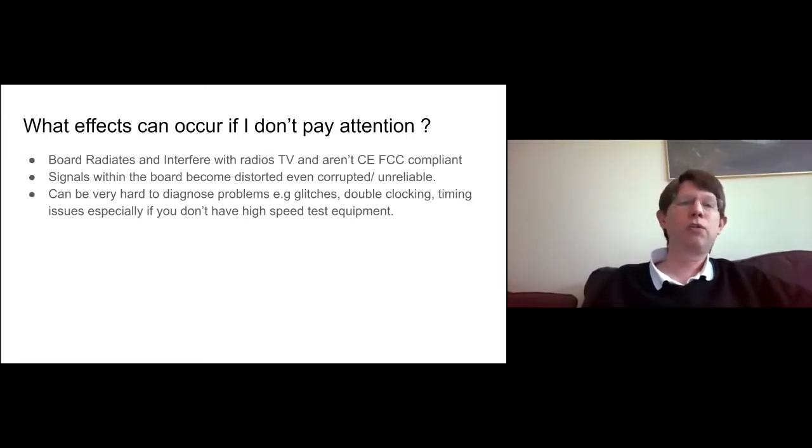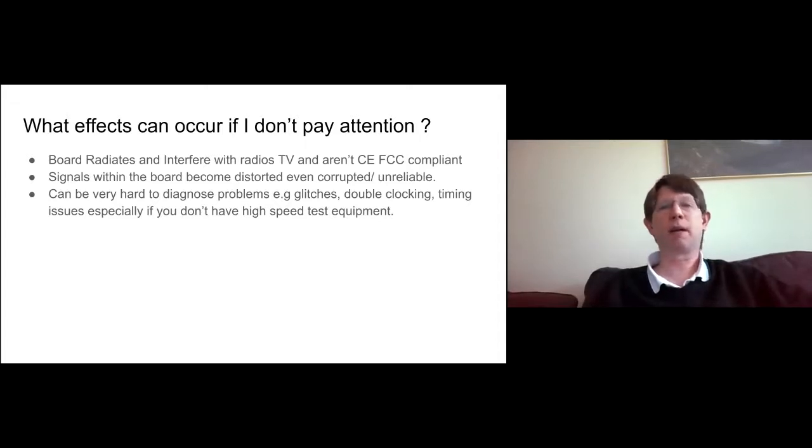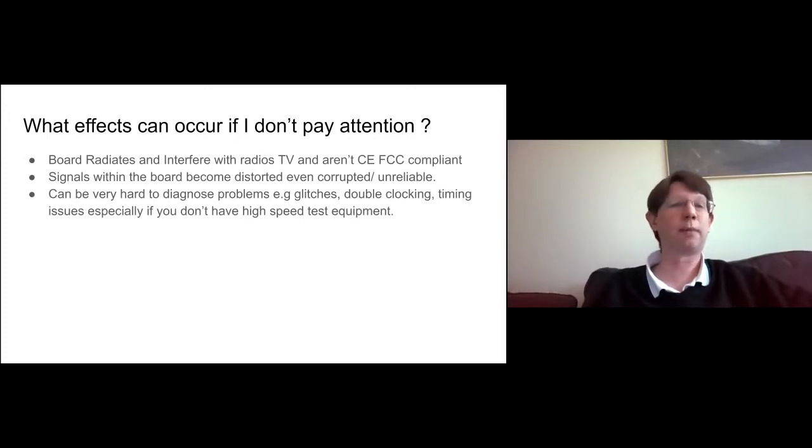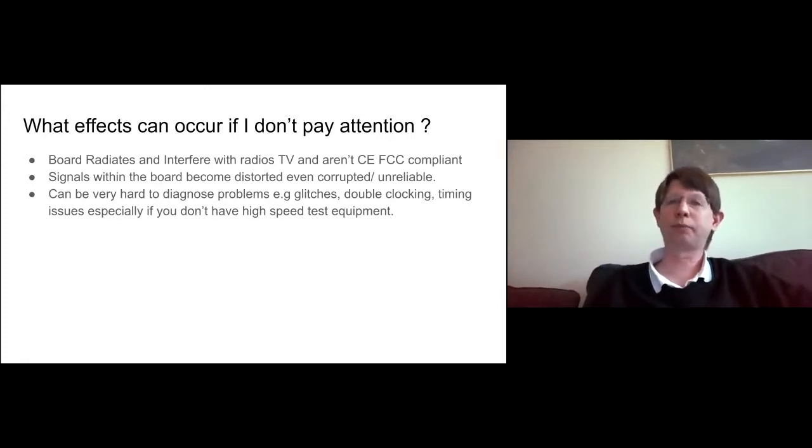But within your world, the signals on the board become distorted and even corrupted and unreliable. And this can be a real problem when you have to diagnose glitches, double clocking and timing issues, especially if you don't have high-speed test equipment. I'm lucky I have access to a lab with some very high-speed test equipment, and I can go and look at these edges and check that they are nicely formed.